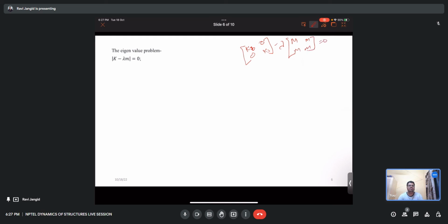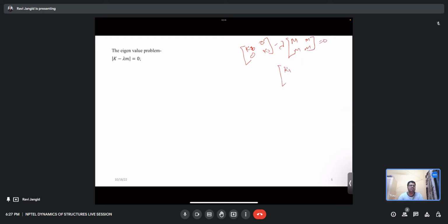So we will write it as Kb minus lambda capital M. Remember this one: with lambda and all the small m, only in the M11 there is a capital M. Then Ks minus lambda small m, and we need to take the determinant of this. So I have written this equation from this. Now write the equation, multiplying this and this.